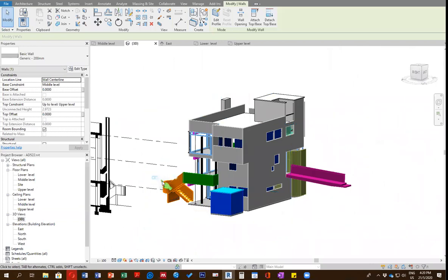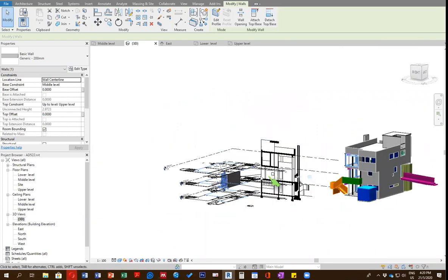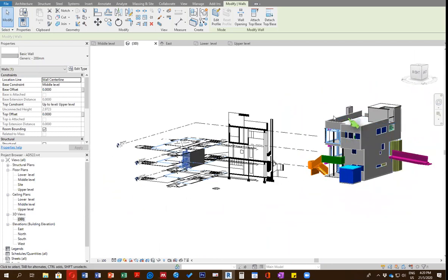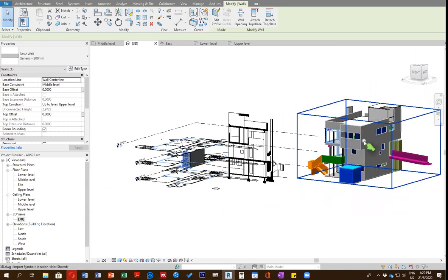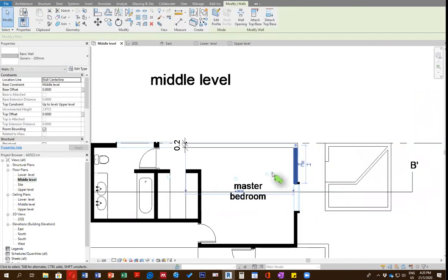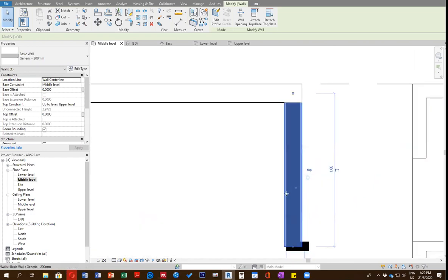Of course, for stairs and ramps there are other techniques to draw. We will go through those, but for this assignment, as explained in the project brief, you need to consider the walls, the windows, these big walls, the roof. All of them, you have to finish in assignment 1 for all levels, of course. And things like thickness of wall should be correct. If I see the thickness like here, for example, this one is a mistake. I have to follow the AutoCAD file for the thickness.